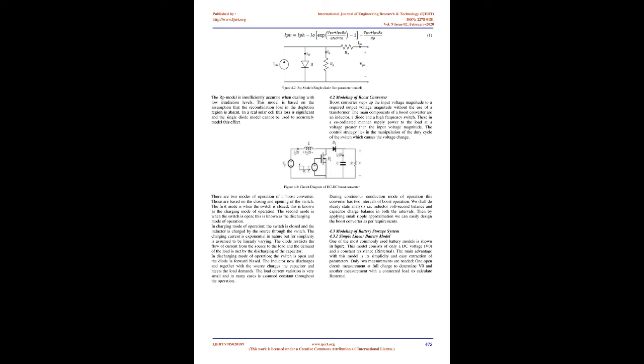When circuits are wired in series, positive to negative, the voltage of each panel is added together but the amperage remains the same. When circuits are wired in parallel, positive to positive, negative to negative, the voltage of each panel remains the same and the amperage of each panel is added.